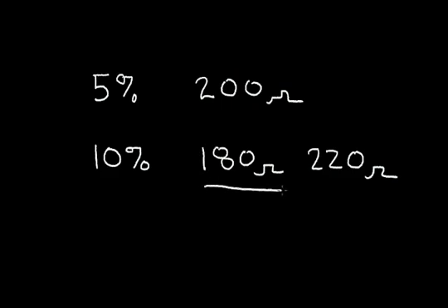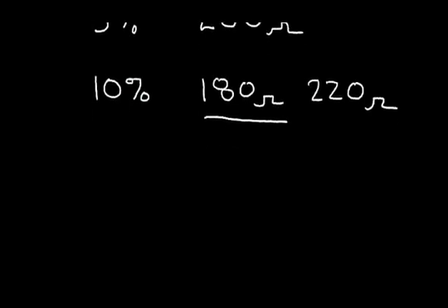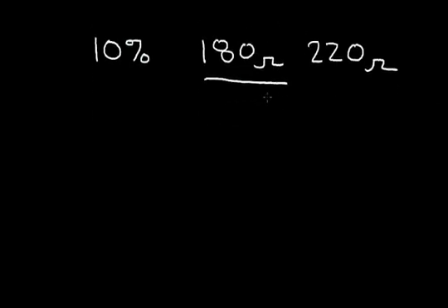So let's consider using 180 ohms. So let's consider, am I going to exceed my 25 milliamps at any time in this LED? So let's say that I have this 180 ohm resistor, my light emitting diode, connected to ground.